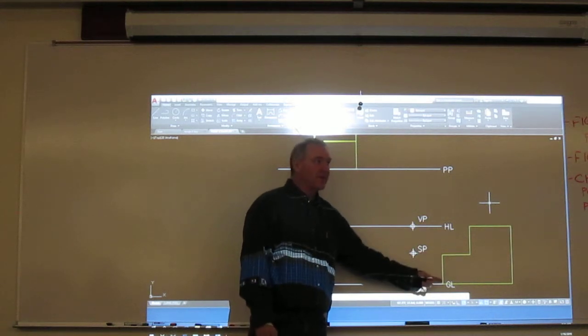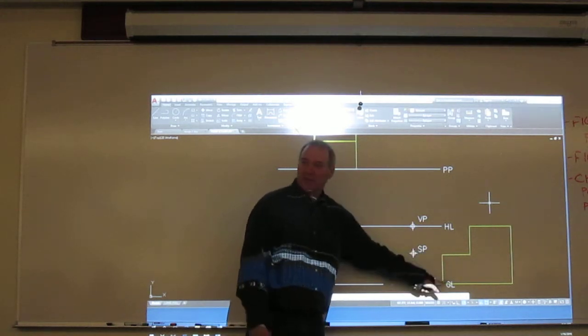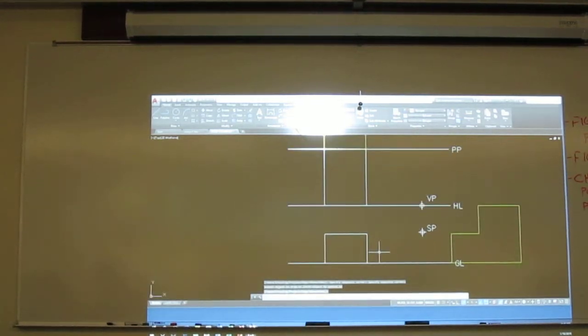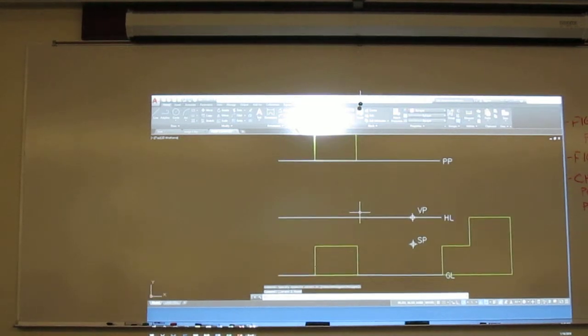So you do have a front view that you should have projected. We can just take that view and bring it right over, or you can project for it. Since I just used the copy yesterday, I'm just going to project for it today. I'm using orthographic projection here, since it is true size right on the picture plane. So I'm going to take that over and bring my height. Then I'll do a little trimming. So that's gone, that's gone, and another line right here. Match properties. So there is my front view, that rectangle.